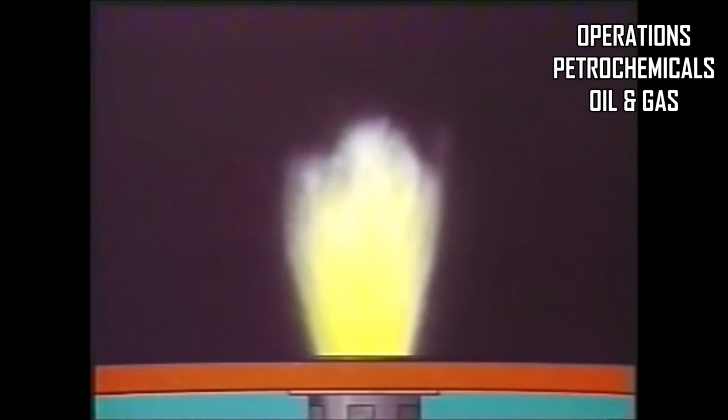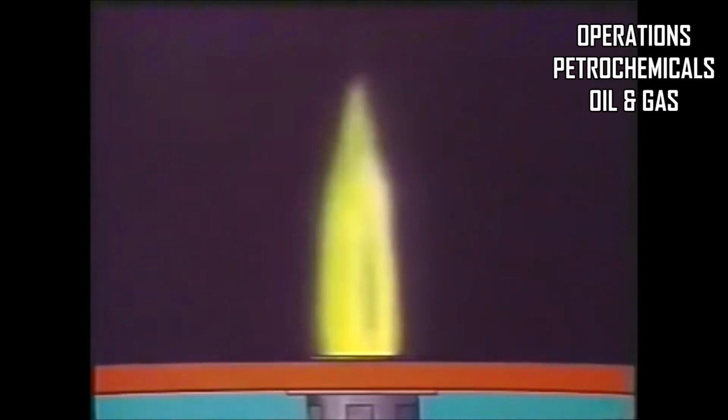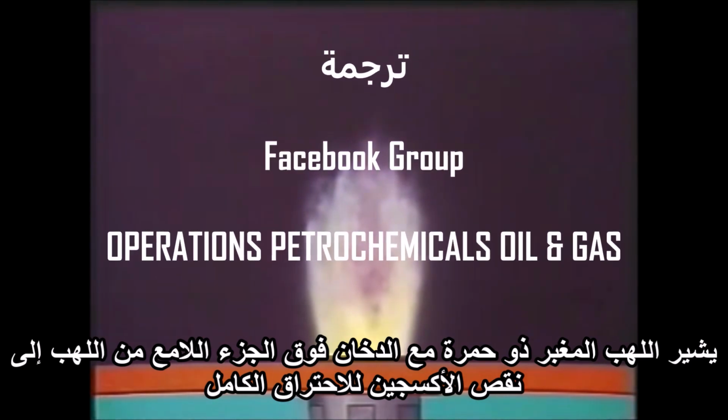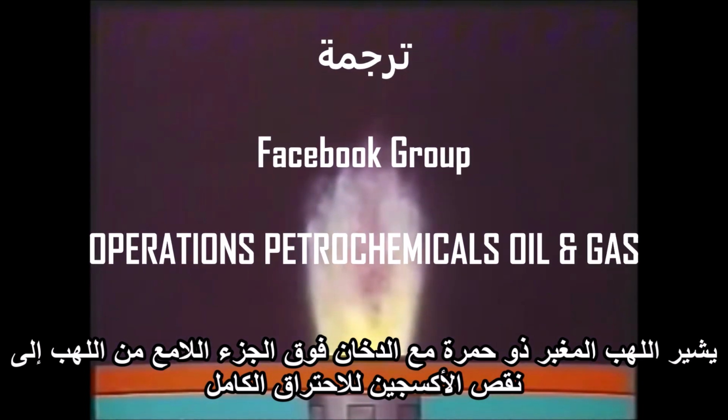Let's look at some other undesirable flame patterns and consider the causes. A long, smoky flame is caused by insufficient combustion air or insufficient atomizing steam. The flame may be shortened by increasing primary or secondary air or by increasing atomizing steam. A thin, fluttery oil flame indicates too much atomizing steam is being used. A reddish, dusty flame with smoke over the bright part of the flame indicates a lack of oxygen for complete combustion.